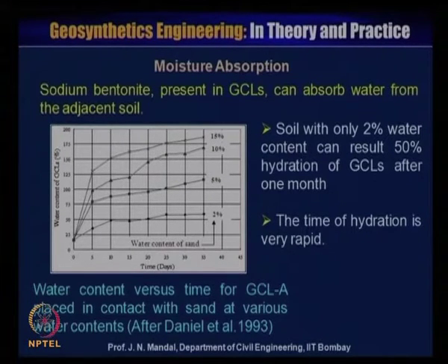Sodium bentonite present in the geosynthetic clay liner can absorb water from the adjacent soil. Here you can see water content versus time for a geosynthetic clay liner A placed in contact with sand at various water contents. Soil with 2% water content can result in 50% hydration of the GCL after 1 month.